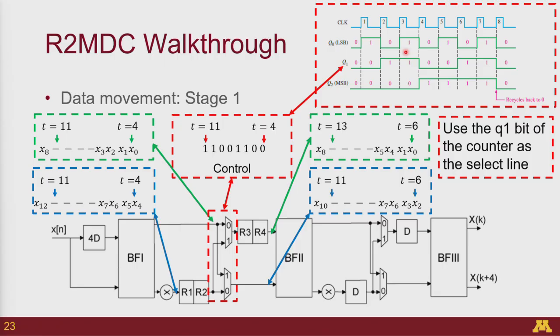Okay. How many lookup tables are there for all the twiddle factors? So it depends on which type of FFT we are implementing. Let's say we are implementing a standard radix 2, generally we need up to n over 2 twiddle factors. So basically, if it's 8, we would need up to W3. But in reality, if you're more constrained, you could represent it in half of that, because you can represent sine in terms of cosine.